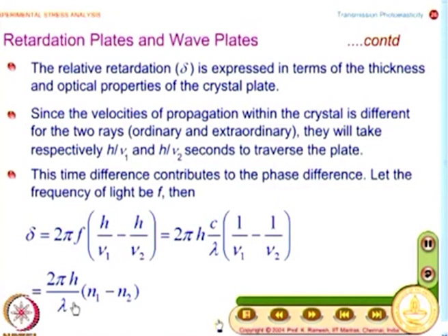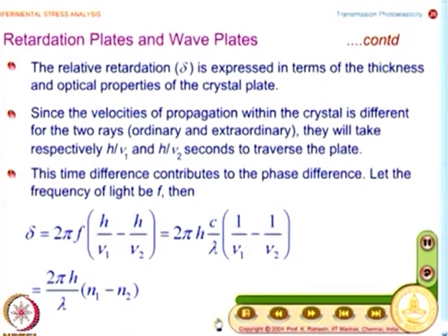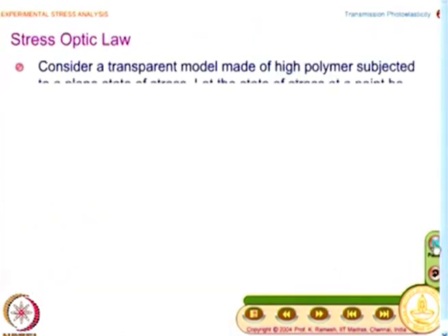So, what you have to understand is in photoelasticity why the wavelength is important; monochromatic wavelength comes hidden in the expression. Now, what we will do is we will go back and see what great scientists have contributed, how this could be related to sigma 1 minus sigma 2, more by induction rather than clear mathematical development.